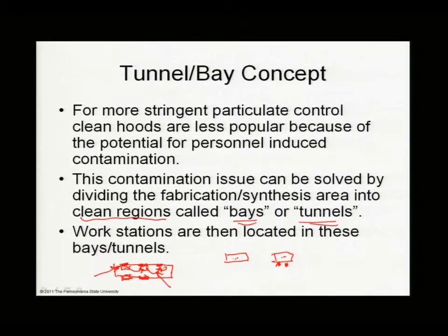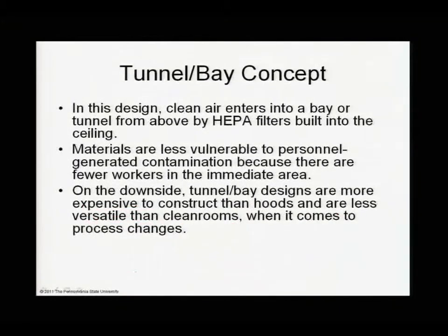Then the workstations are located in these bays or tunnels. In this design, clean air enters into the bay or the tunnel from above by HEPA filters. So you have your HEPA filters on the top of this area. Then you have your workstations, which may have their own HEPA filters.